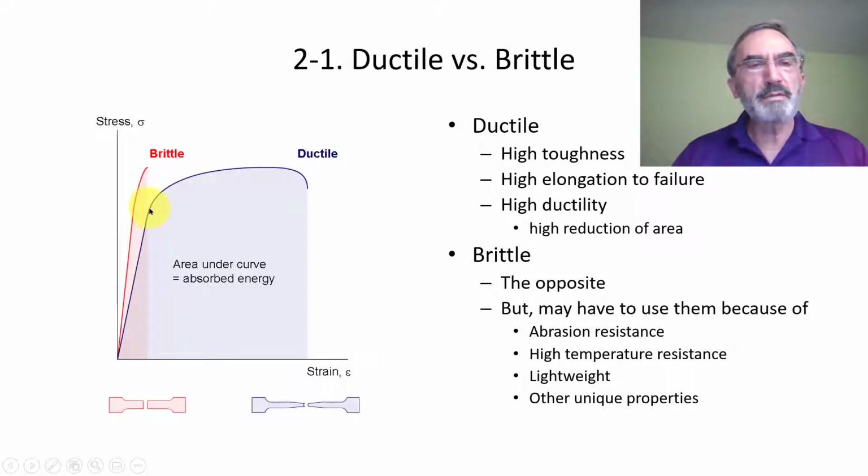The structure will suffer permanent deformation because if you go over there, when you unload you go parallel to the original line and you get this much permanent deformation from here to here. That means that you're going to have an indication that something happened. So the fender will be bent.